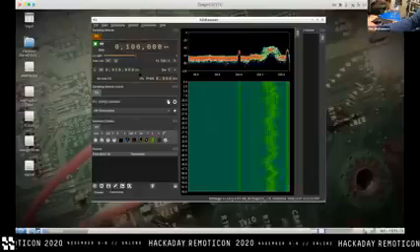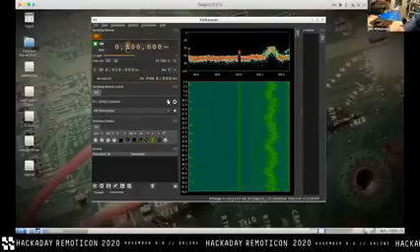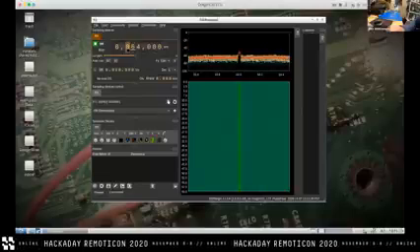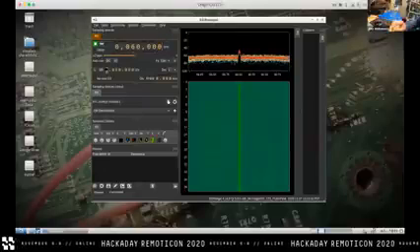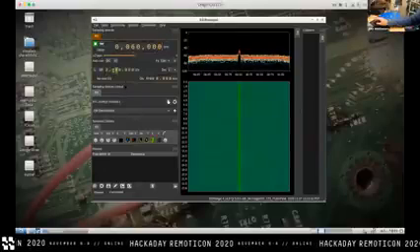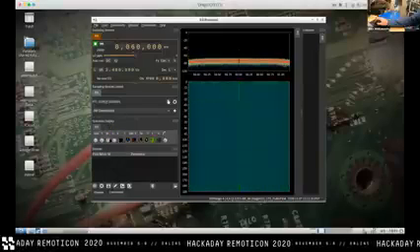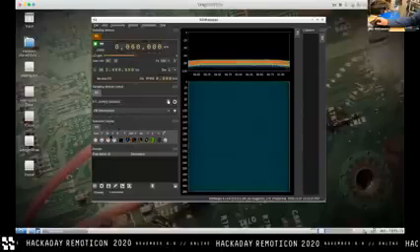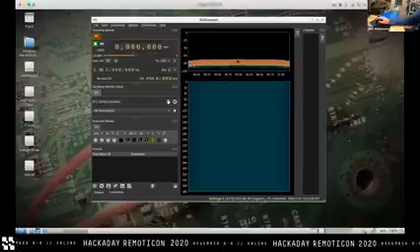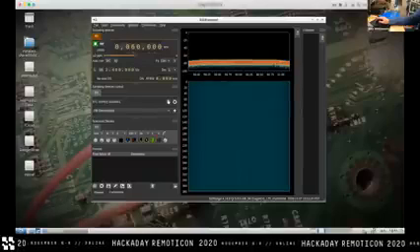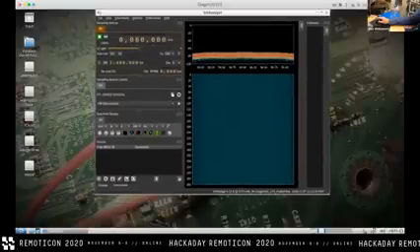Before we go there, I'm just going to quickly retune this SDR to 60 megahertz. And I know this VM can handle it, so I'm going to crank up the sample rate and everything. And we'll add some FFT bins. This still seems pretty performant. 2K. Okay, cool. Actually, this is an interesting point. When I cranked up the FFT, that peak got very much narrower. So it's probably some unsuppressed artifact of the math or something that I'm just not quite understanding.